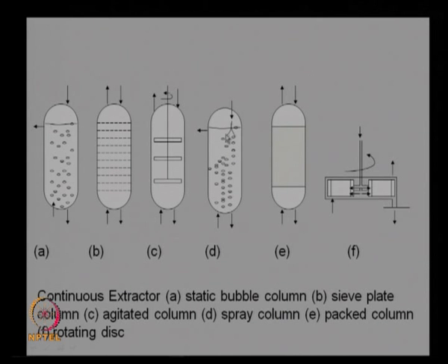That means one of the liquids is sprayed. This liquid can be your solvent or it could be the heavies, it is sprayed and again it creates fine bubbles. When you create a fine bubble, the mass transfer area is very large. As you know, mass transfer area plays a very important role in the kinetics of extraction. So the finer the bubble, the more the mass transfer area, so the higher the rate of extraction.